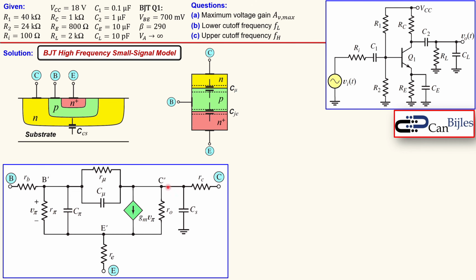It is quite complicated. You can see that we have a lot of components here, so let's go one by one through what we actually see. For the small signal parameters in the high frequency, we see here the base as we see it from outside, but you also have the connection inside, which is called B prime. In between you have this zero bias base ohmic resistance, the RB.